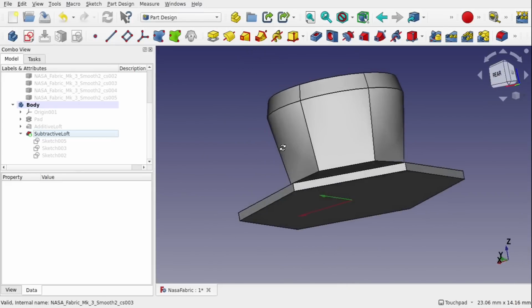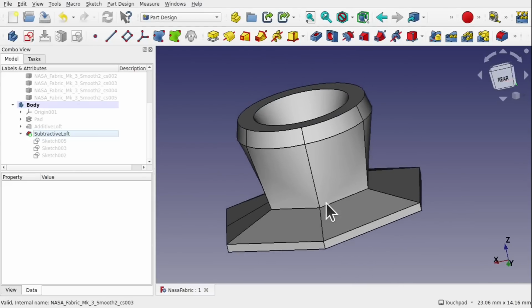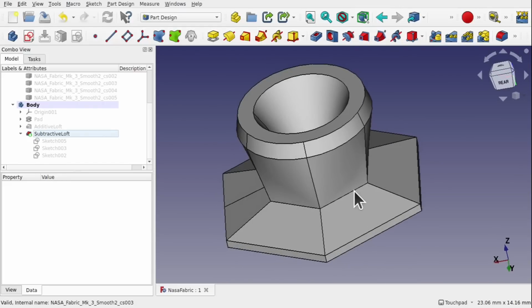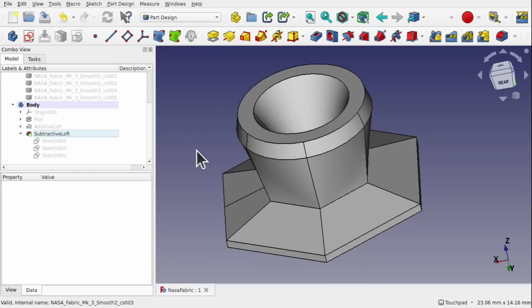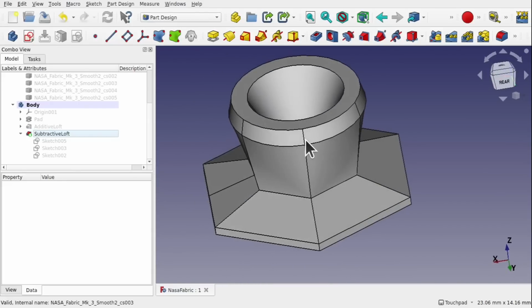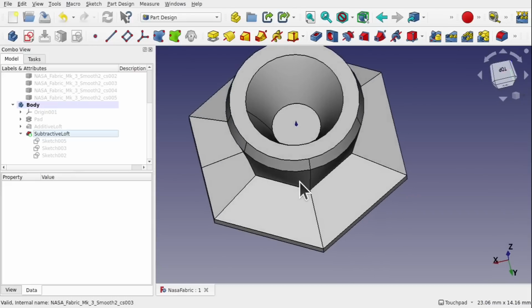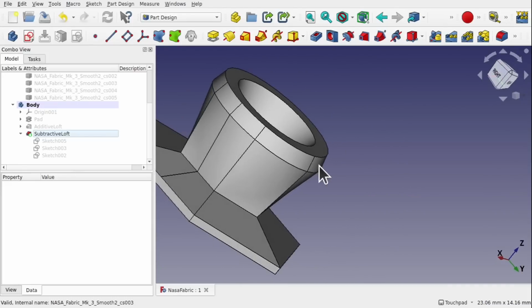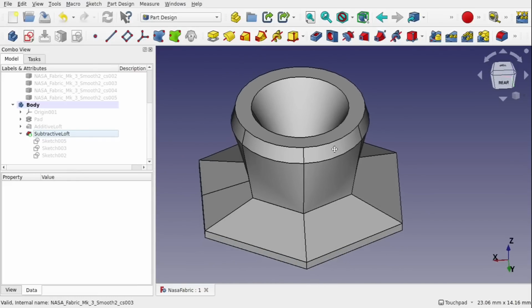We just need the arms now. There are a number of ways of doing the arms. The way I'm going to do these is use something called Curves Workbench. That's available from Tools and Add-on Manager, and we'll find the Curves Workbench in there. We'll create a freehand B-spline from here, radiating around to this point, and create a profile and attach it to that. We need some adjustments for that freehand B-spline because we need to make sure that the profiles actually sit inside this object, and the Curves Workbench gives us the tools to do that.